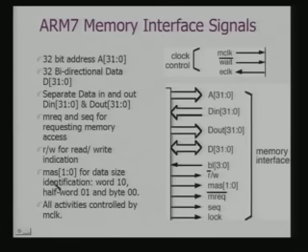If you remember, we started with the basic model where we had size as a signal. This is a 2-bit signal because it indicates different sizes. It indicates the size of the data which is to be transferred over the bus. And all these activities are to be synchronized with regard to the MCLK, that is the system clock.